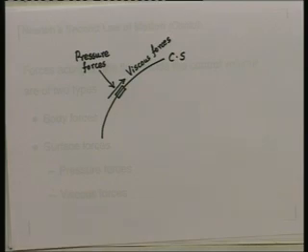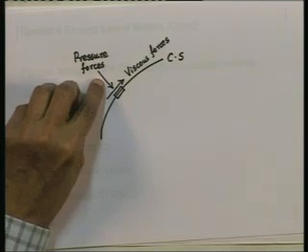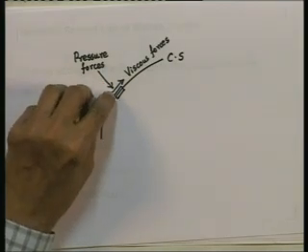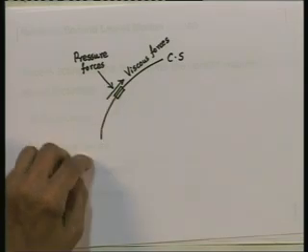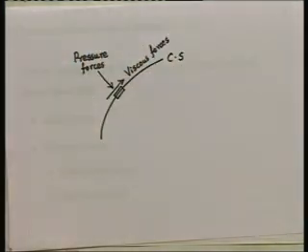So, when we say x direction forces acting, what we mean is the components of these pressure and viscous forces act in the x direction acting on this dAi and summed up over all the dAis which comprise the control surface of this control volume. That is what we mean by the surface forces exerted by the surroundings on the fluid inside the control volume.